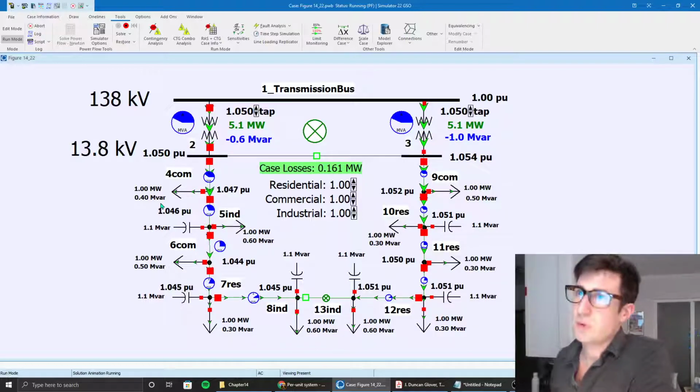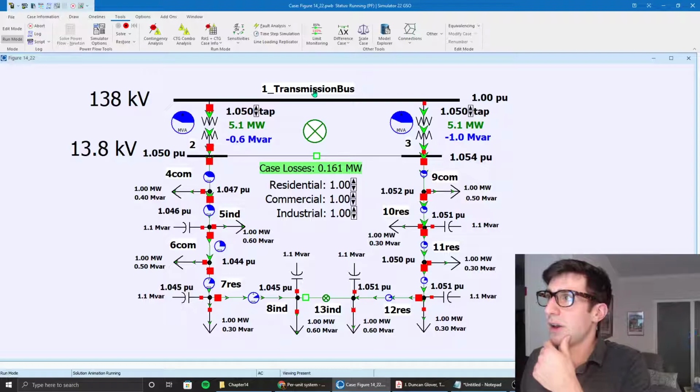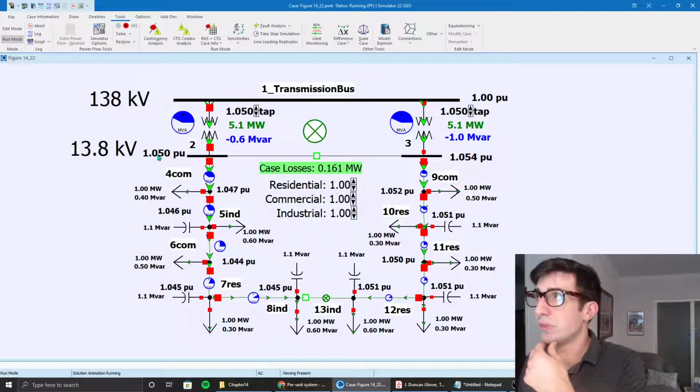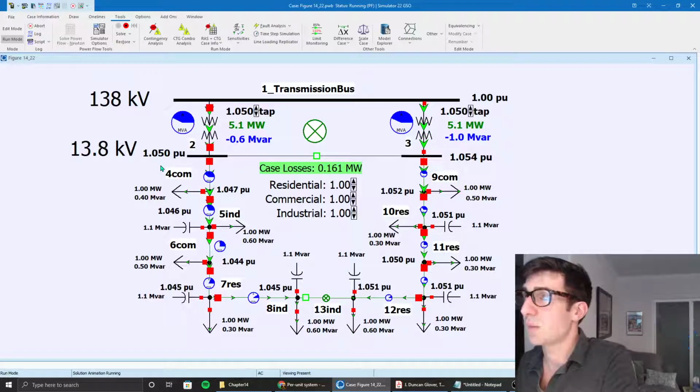So what we're doing, just to give you a rundown of this diagram, is we're starting from a higher voltage and moving high voltage, low current. Then we step down to the distribution level at a substation, 13.8 kilovolts, which is standard distribution. It's most common in the United States. It's a safe distribution level to deal with, and it's most common amongst modern distribution systems.